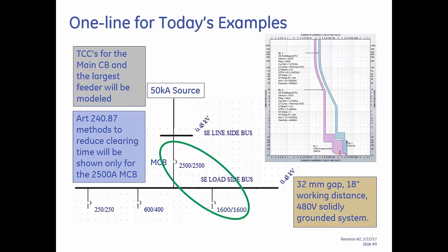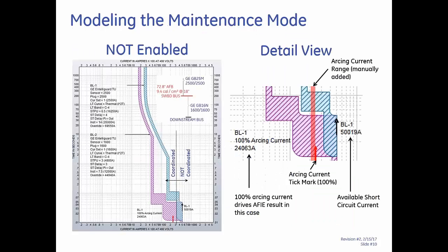Okay. So on the left-hand side of the slide we're now looking at, we're seeing, again, the baseline setting. And the first thing I want to point out is there is one part of this graphic that is added in PowerPoint, not part of what EasyPower does, and that's the vertical dashed line I'm showing, with the arrow going to the right showing a non-coordinated region, and the arrow going to the left showing the coordinated. So what I'm indicating there is up to that point, and that dashed line represents where the instantaneous parts of the curve start to overlap.